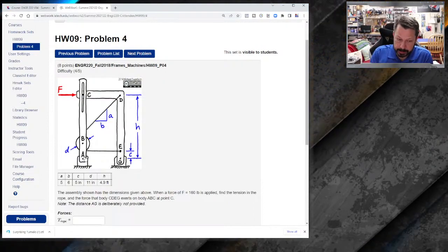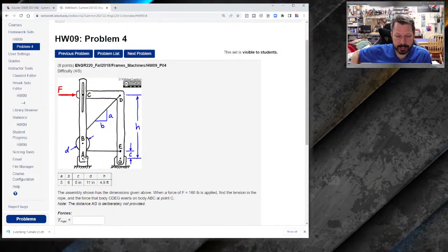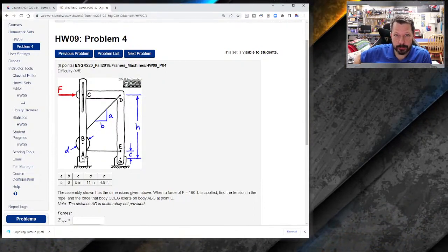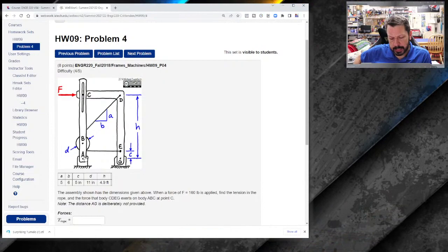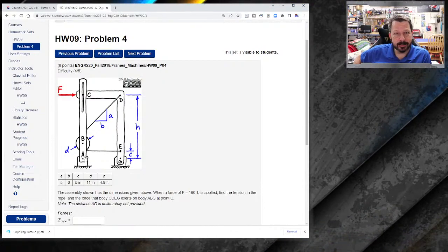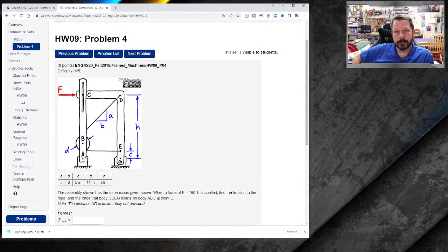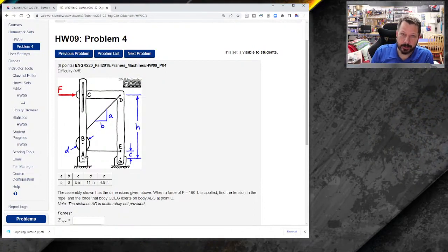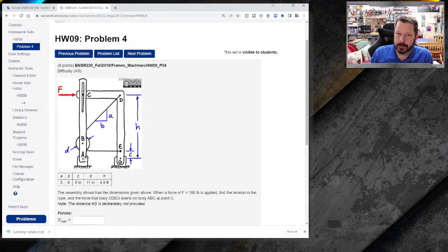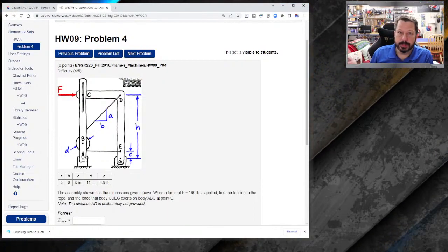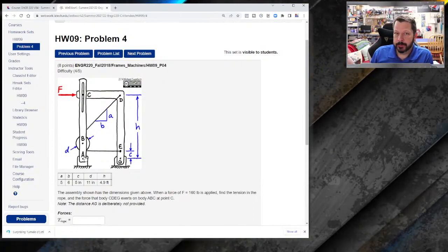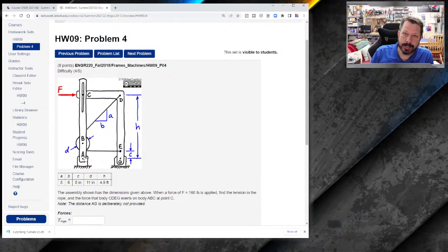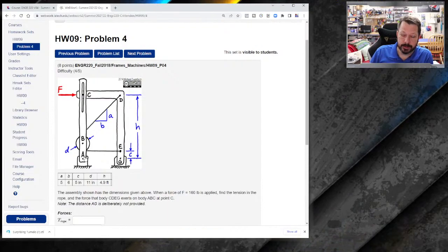Normally in statics, when we're dealing with statics and strength of materials from a static equilibrium point of view, two pins is a key that there's something different, because two pins create 4 external reactions, and we only have 3 equilibrium equations. That means we can't solve all of the external reactions first.